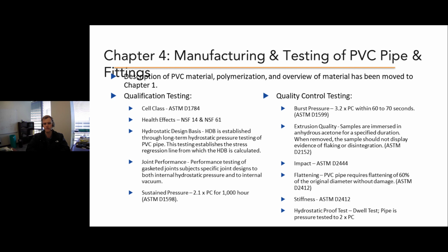I believe the percent was, if you're flattening the pipe fully, nothing's going to flow through there anyway. So it's kind of an unrealistic test because it's functionally pointless. So a test up to 60% of the original diameter was seen as low and all that. And of note there for PVC pipe, the action limit. So you definitely have a design limit well under the point that the pipe is tested to.